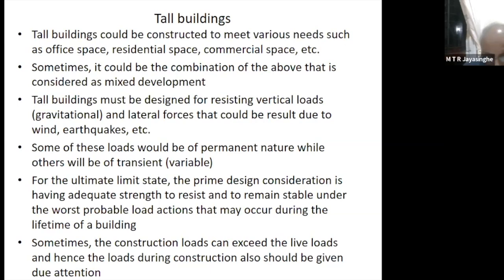But today, most cement contains 60 to 65% tricalcium silicate and only 5 to 10% dicalcium silicate. So what is the end result? Today, after 3 days, 4 days, you get enormous strength. After 7 days, you can get 28 days strength. Then after 14 days, the strength gain is very slow, very slow. And you will find that 28 days strength is available in 7 to 10 days. And you must know the reason.